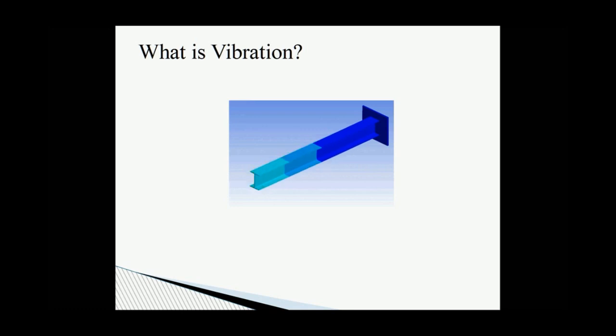This is important in design because you will need to know where your modes, where the resonant frequencies of your structures exist, in order to design a system or structure which has modes or resonant frequencies, if possible, outside of your operating vibration range in order to prevent stress to your system. Now, once again, we're going to go into more detail about this later on, but I wanted to get you familiar with modal analysis and modes and system or structural deformation.